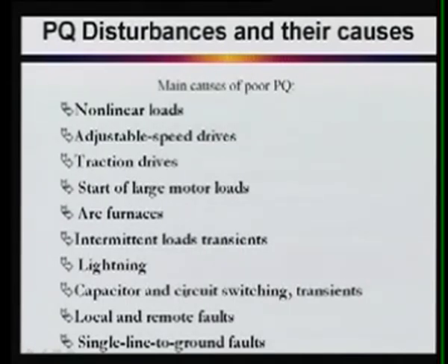But what are the major causes of poor quality? First one is nonlinear loads. Now what are nonlinear loads? All the power electronics driven loads, like converters, if your load is fed through converters, or others like arc furnaces, etc., are nonlinear loads. And these nonlinear loads create a lot of problems for power quality. So nonlinear loads are one of the major causes.